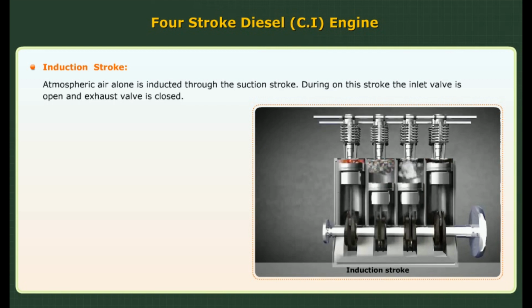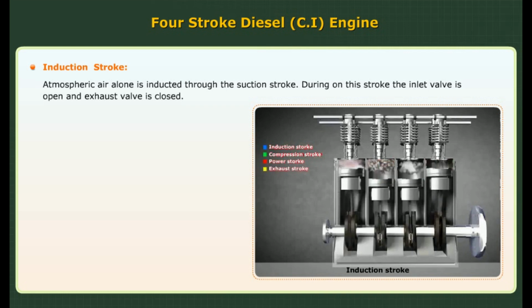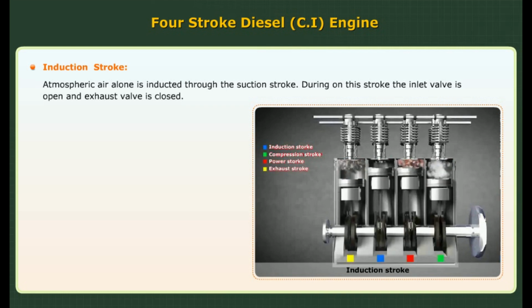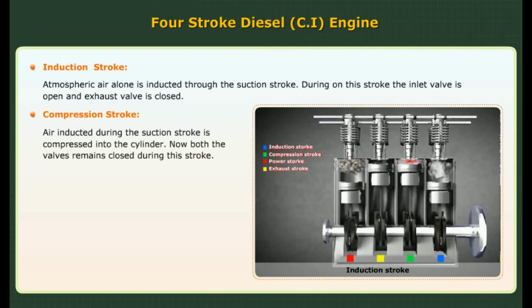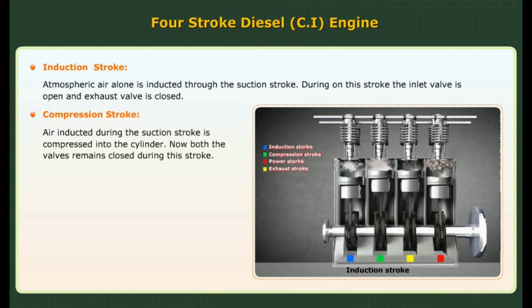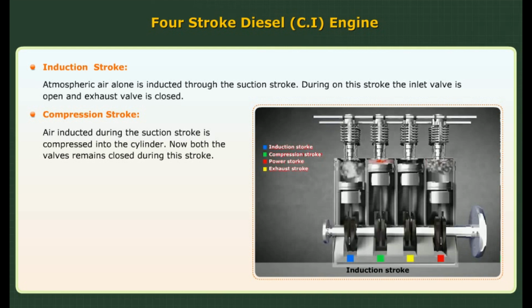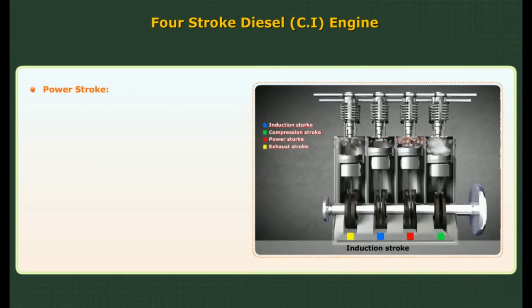Induction stroke. Atmospheric air alone is inducted through the suction stroke. During this stroke, the inlet valve is opened and the exhaust valve is closed. Compression stroke. Air inducted during the suction stroke is compressed into the cylinder. Now, both the valves remain closed during this stroke.